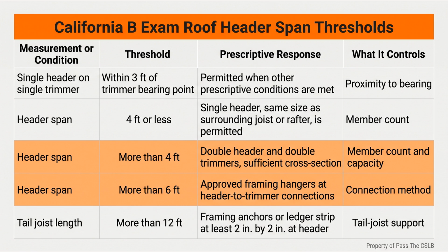The sequence matters. I want temporary support, layout, opening protection, weather protection, hardware, and lumber coordinated before the cut. I also want required inspection or design review scheduled before the work is concealed.